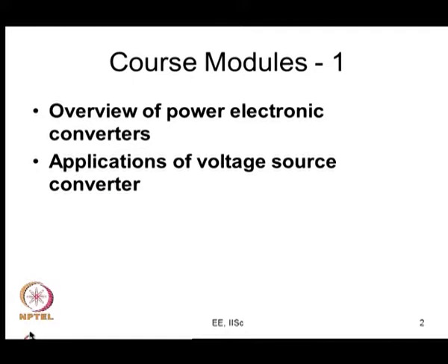I am just trying to recap so that you can have a quick understanding of what happened when, and if you have not followed all the previous lectures, you can go on and catch up with a particular module and so on and so forth. So, what we started off with is actually an overview of power electronic converters. In fact, we started off with how to connect switches and how not to connect switches, that we have to make sure that an inductive circuit does not get opened out or a capacitance does not get shorted and so on and so forth.